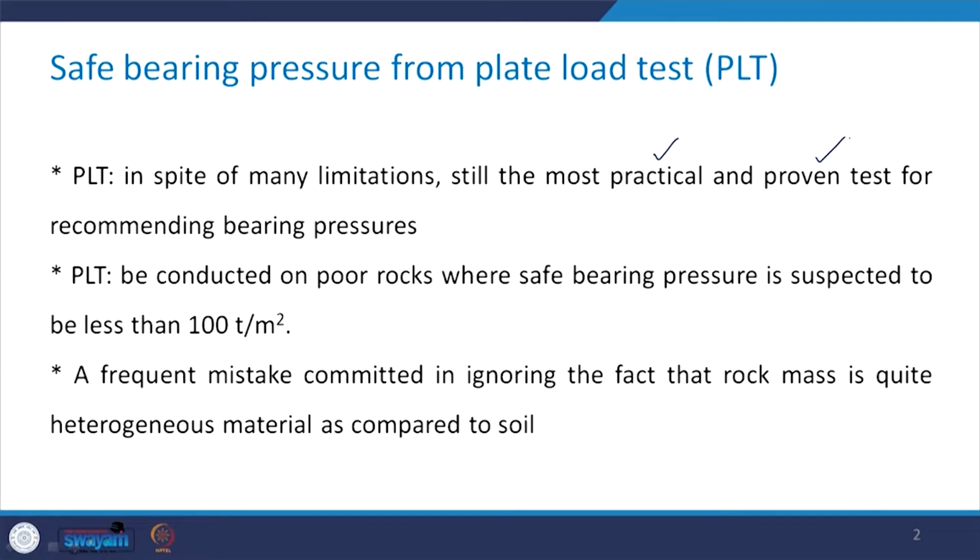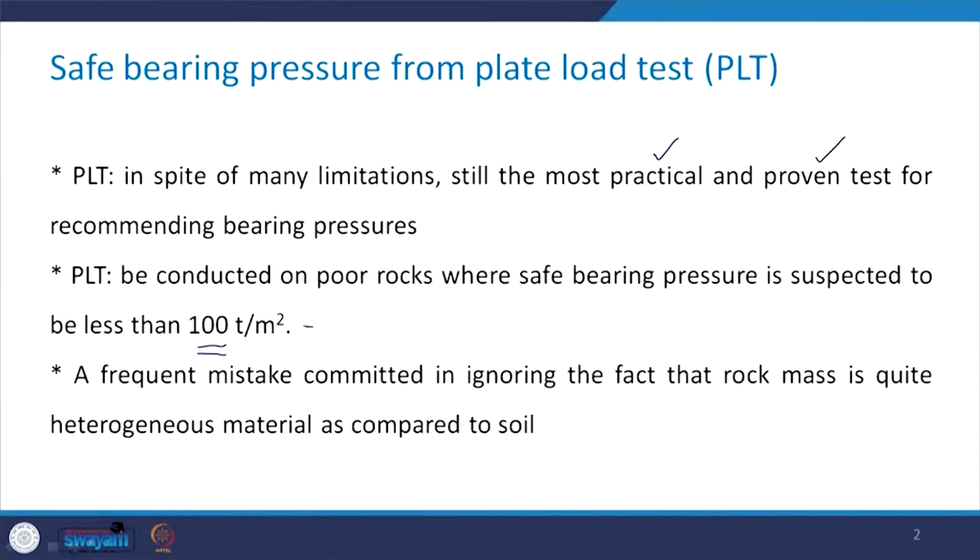These plate load tests should be conducted on poor rocks where safe bearing pressure is suspected to be less than 100 ton per meter square. If you recall our discussion of the previous class, I showed you a table of in which case this plate load test would give us a reliable value of the safe bearing pressure. So this is the condition that one needs to keep in mind.